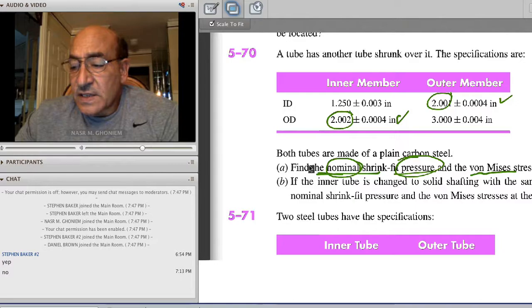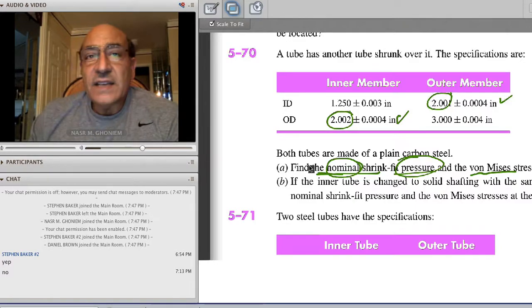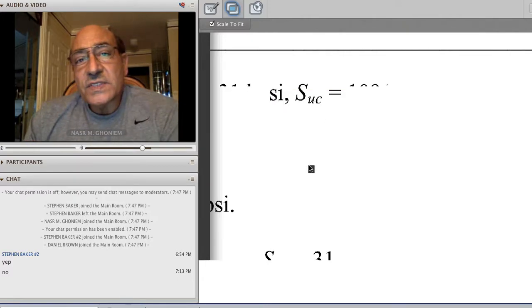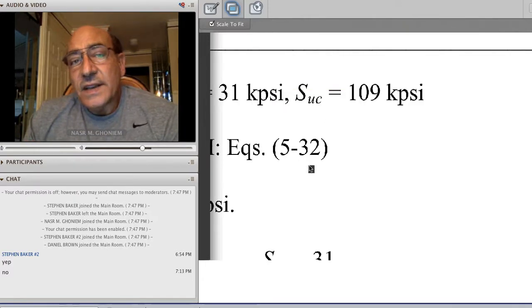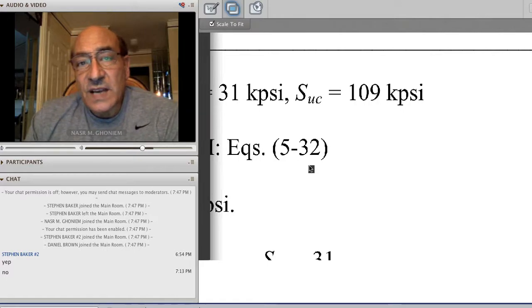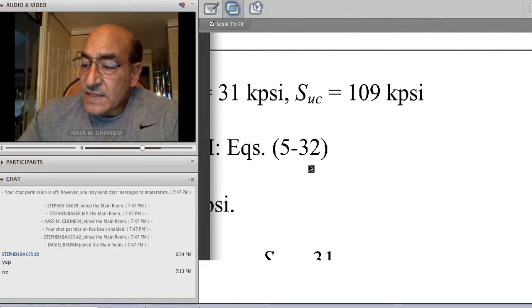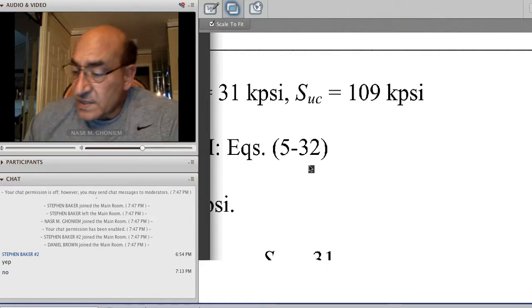The steps are following the same situation that you get. First, you convert forces to stresses, and now you have to think a little bit harder because you have to find where the stresses could be the highest and how you can combine them to find the von Mises stress and determine if you have any failure. So that's kind of the situation here.